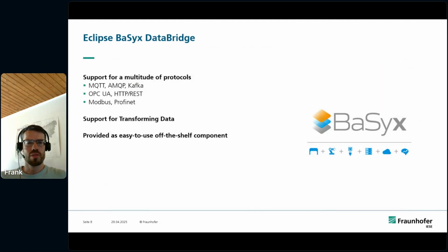Another component that I would like to very briefly speak about is the Eclipse BaSyx data bridge, which we are providing again as a Docker image, as a microservice that integrates arbitrary data sources with asset administration shells, like for example MQTT, Kafka, OPC, but also industry typical protocols like Modbus, Profinet, and so on and so forth.